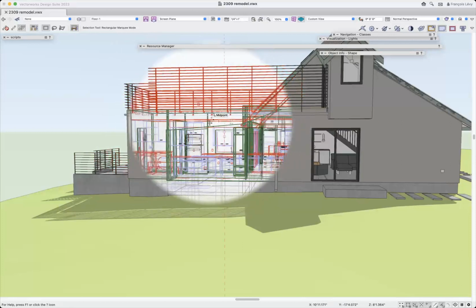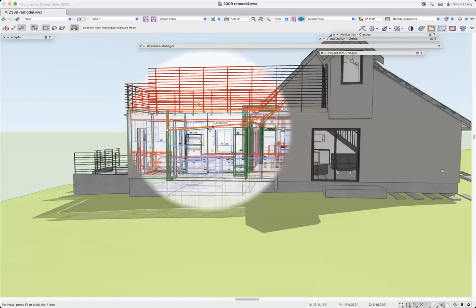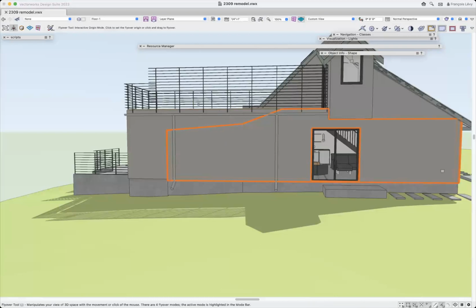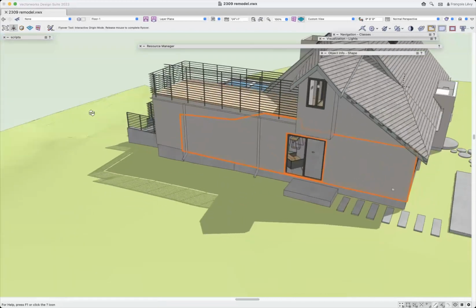All right, so I don't know if you can see, but if I just click on here, this is the old roof line of that little shed addition, and then there's just a piece of wall stuck up here. So that's a new wall, but this is an existing wall, and you can't really tell, right? For this existing wall, I didn't have a component for the old siding, then demo that component and add a new component of stucco. I just show that wall in its final form with a weather barrier and stucco and so forth.